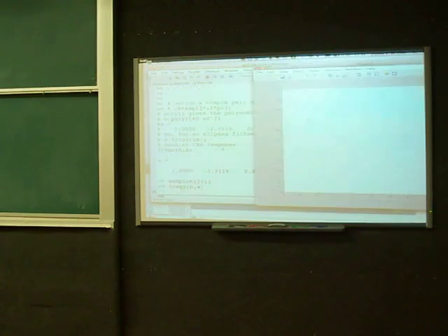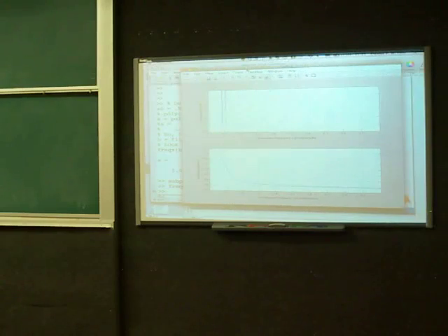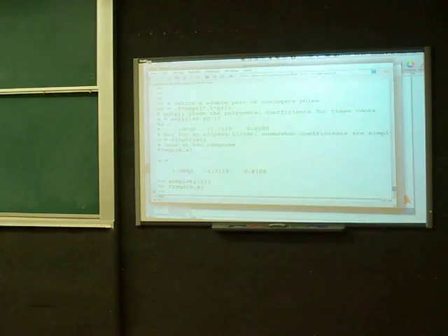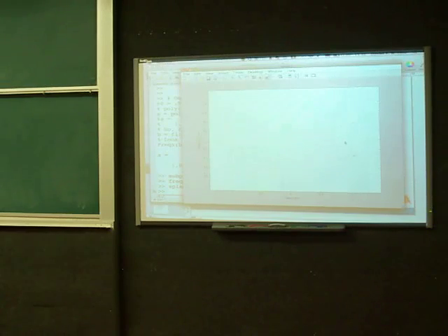Okay. So this is the magnitude response, and this is the response to the filter. The magnitude is 0 dB. It's a flat filter apart from these numerical errors. But then we have this phase response, which is non-flat. If we look at it in the z-plane, then we have these two poles and these two reciprocal zeros to give it this is now a second order all-pass system.